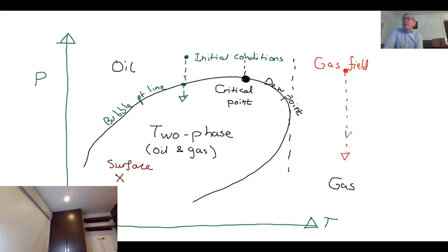the fluid simply expands and expands and expands. So if I'm to the right of this two-phase diagram, I have a gas field. And the way in which I operate that gas field, because I don't hit a phase boundary, I don't get some problems with two phases. I'll talk a little bit later about the problems with two phases when we hit the dew point, but let's keep with this simple case first. That's the way of operating a gas field.